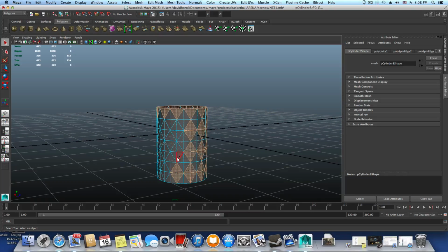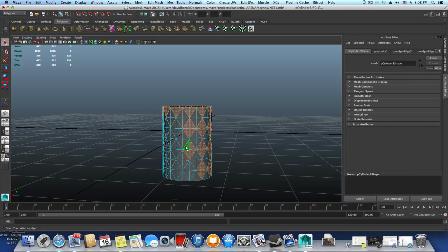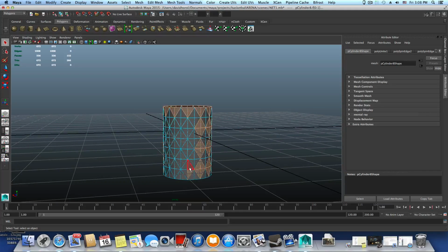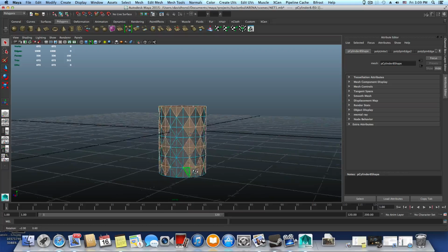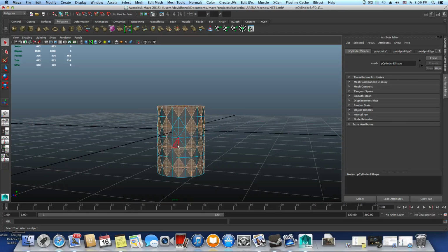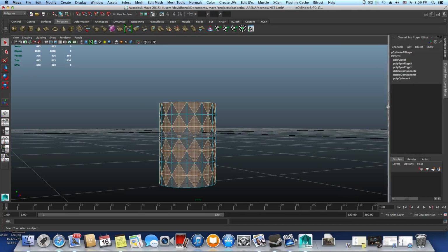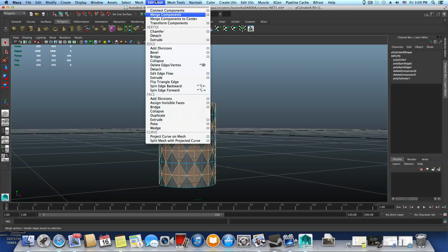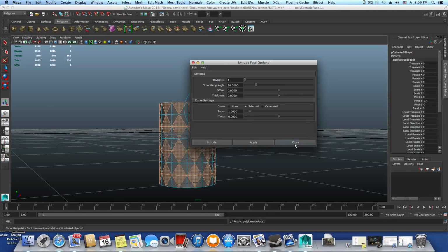Okay. Grab these. Grab these. Grab these. Okay, so you see all of them have been selected. I'm gonna expand the channel box here. Click on this. And I'm gonna click Extrude. Now make sure that you go over Edit Mesh, Face Extrude option box, reset the settings for whatever has been there, and click Apply. Okay, close.